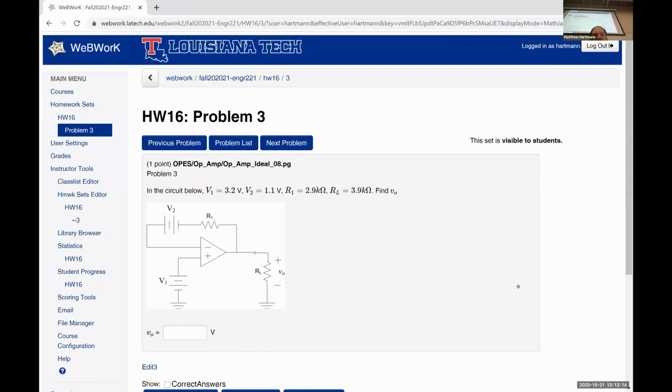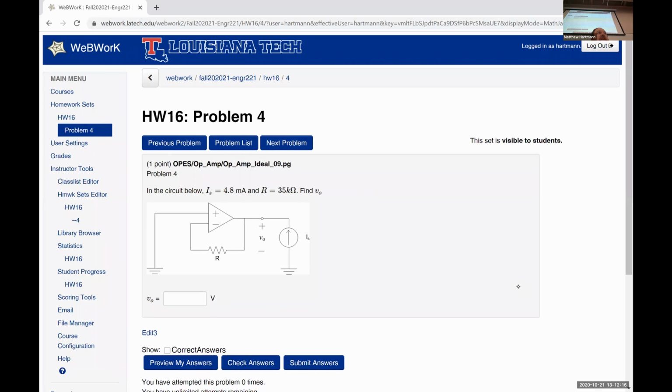I mean, this stuff is fair. Like I said, the problems that I put on the board were significantly more difficult than these. I like this guy because it's mean. What's the voltage drop over the resistor have to be? 0. So if we did a Kirchhoff's voltage law loop starting at ground on the non-inverting input terminal, we would have 0 plus V out is equal to 0, which means V out is equal to 0.